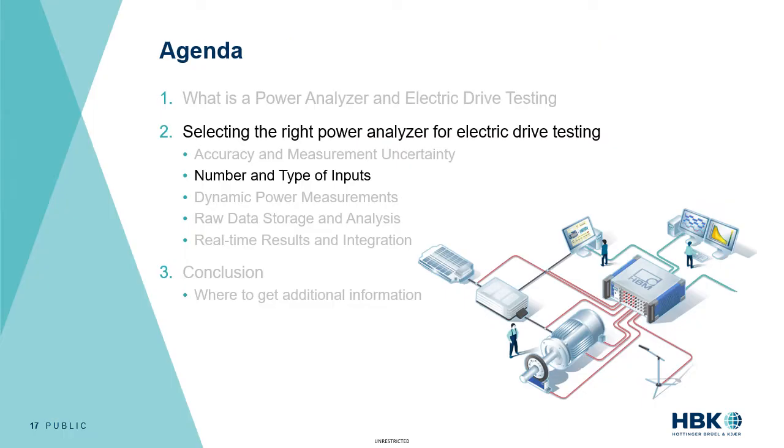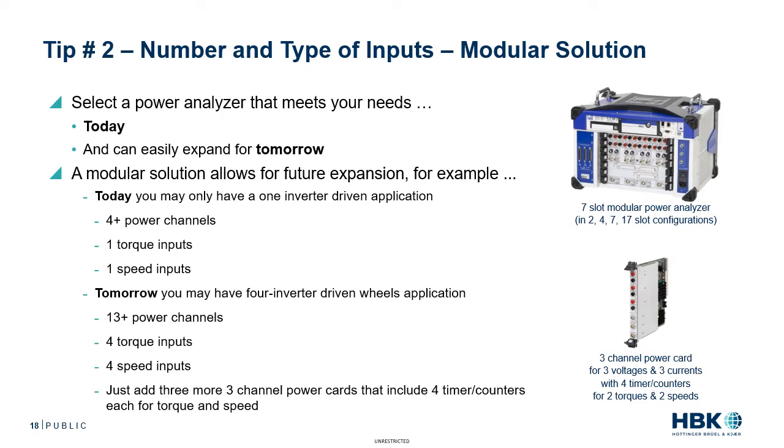Well, our next topic when selecting the right power analyzer for electric drive testing is the number and type of inputs. Ideally, you'll want to select a power analyzer that meets your needs today and can easily be expanded for tomorrow's applications. A modular approach means that your power analyzer can be easily expanded with more acquisition modules, offering more power channels and timer counter inputs for torque and speed measurements, making your system future-proof.